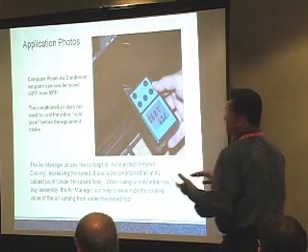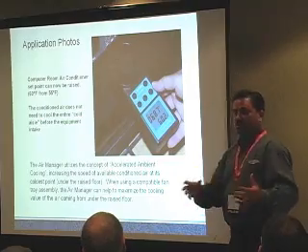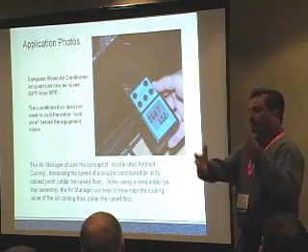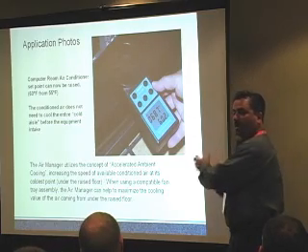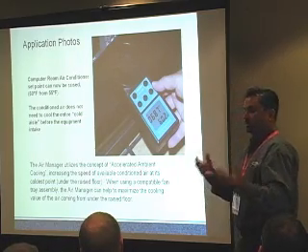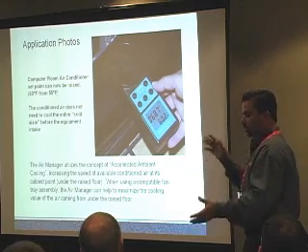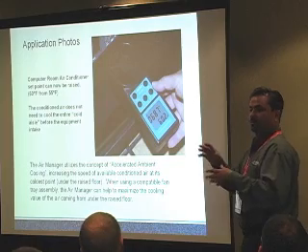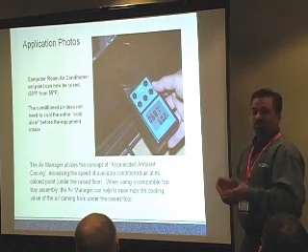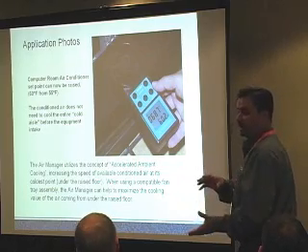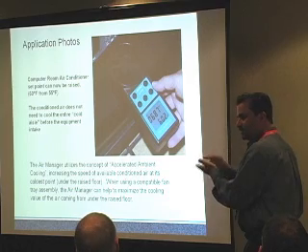What we're trying to do is, instead of having the conditioned air mixing within the cold aisle and then having to get pulled through the mesh front door, go through the equipment, and then get out the back of the cabinet in the hot aisle, that's traditional hot aisle, cold aisle. We're trying to minimize that and slowly push those two, the hot aisle and cold aisle, into the cabinet. Therefore, you don't have to cool the whole room, just cool your equipment. That's the whole purpose. The better you can get that cold air to your equipment, that 70% bypass starts getting minimal.